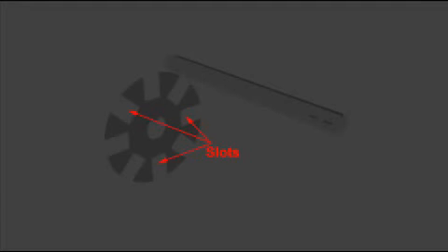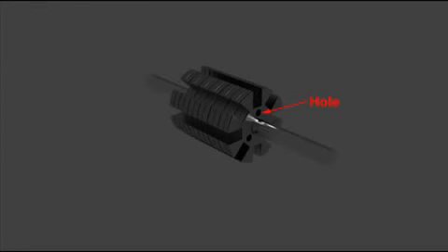The slots are either die-cut or punched on the outer periphery of the circular core. The keyway is located on the inner diameter. The slots are normally open type and usually placed parallel to the axis of the armature, but are also sometimes skewed at a small angle to avoid vibration of teeth. The lamination stamping of the armature is usually punched with holes near the shaft to give longitudinal ventilating ducts. Air is drawn in through these ducts to provide effective ventilation.